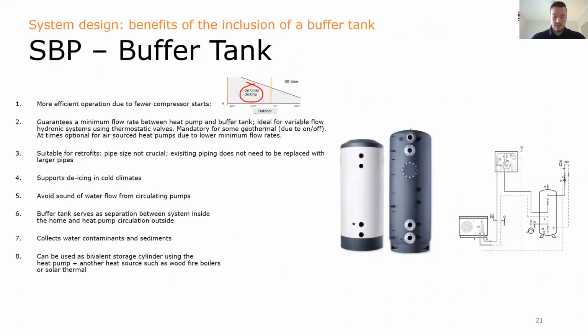Okay, gotta speed it up a little bit. Design, let's look at buffer tanks briefly. One of the big advantages of having a buffer in the system is, as I said before, the clicking on and off can be minimized because we're storing energy in the buffer, which means we can release that energy throughout the day without the heat pump having to come on and off and on and off. So a little bit of efficiency will be added to the system there.